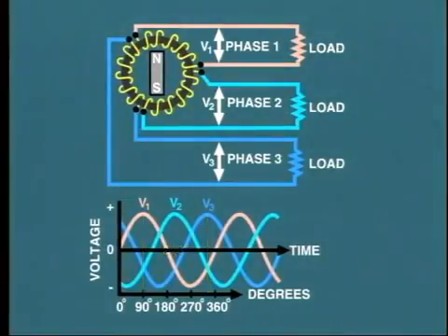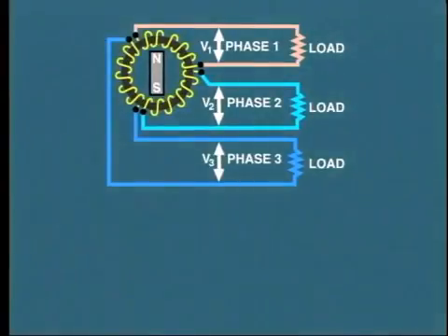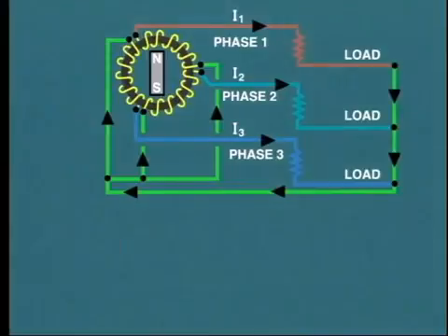So what we have in effect here are 3 independent windings supplying 3 independent loads, but each using a common iron core and rotating magnetic field. Almost 3 generators in one. But there is a further advantage. By connecting one end of each stator winding to a common neutral point, we can provide one single return conductor for the circulation of current from all 3 phases.